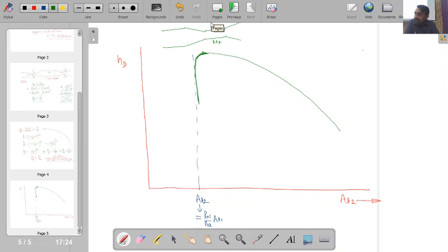This is one situation. Another situation is, if I keep on increasing A2, if I take a larger value of A2, then what will happen? This is quite evident. If I increase the value of A2, what will happen? Ultimately, this convergent section is providing me over here a sonic condition.